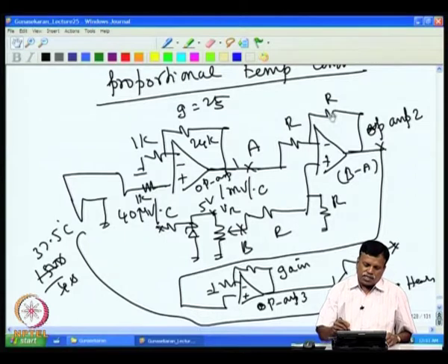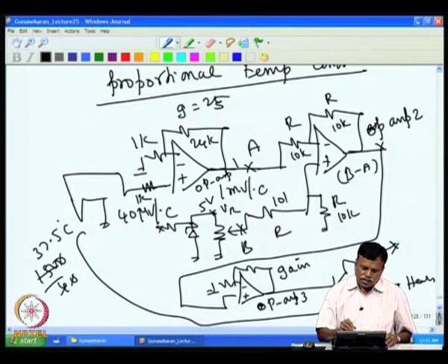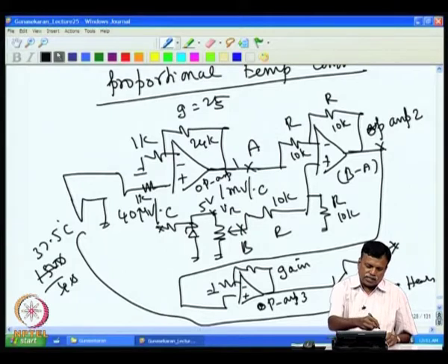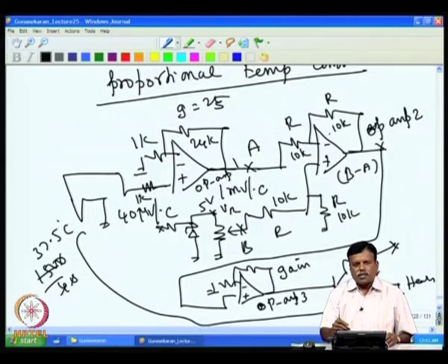Of course, the resistance values used should not be very high. So, for example, I need not put a very high value; this value is to be 10K. One thing: if these resistances are not matched, which we discussed earlier when discussing constant current sources, say if they are 10Ks, they may have 1% error if I use 1% resistors, and they may have 10% error if I use 10% tolerance resistors, but then that will act as a common mode error.